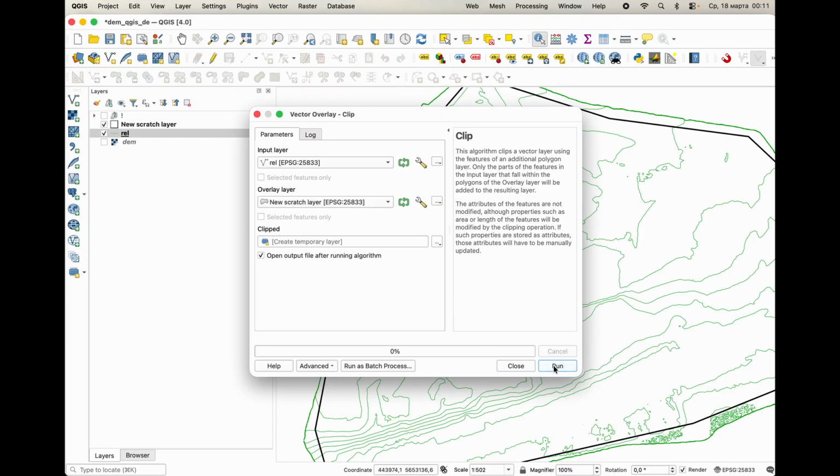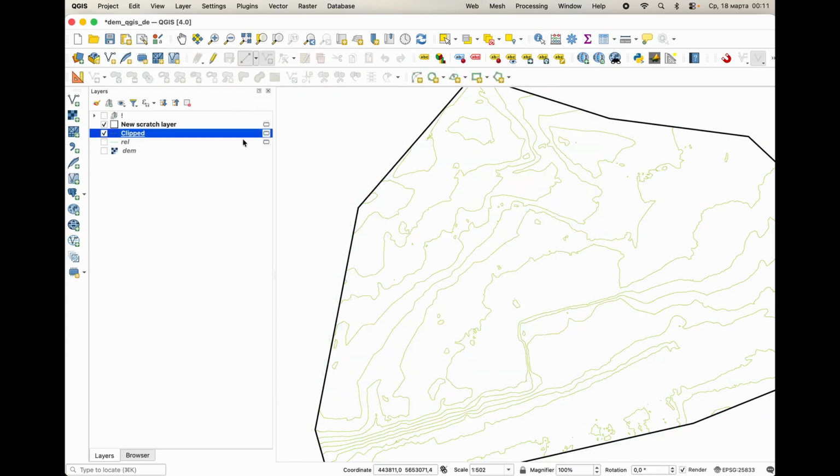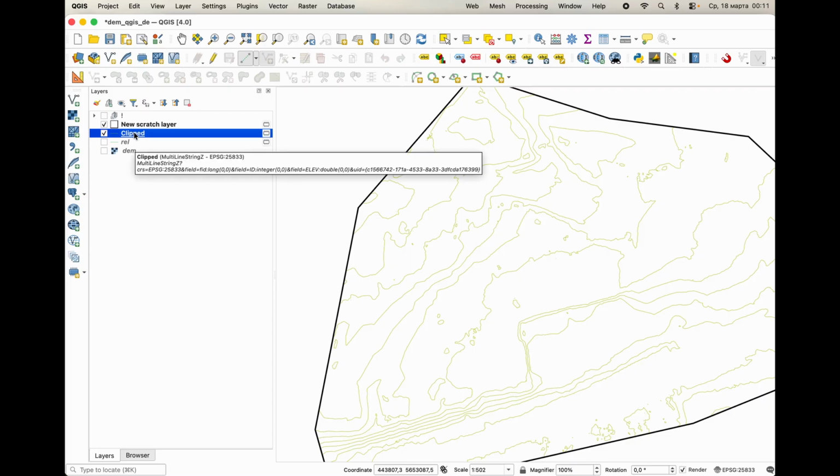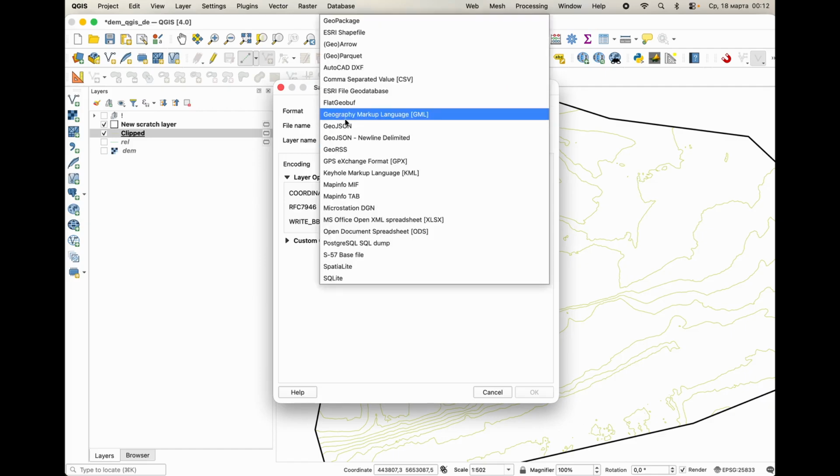The contour lines can be stored in almost any common vector format, depending on what is needed later in the project. For example, we can save them as a shapefile, geopackage layer, or another standard GIS format. At this stage, the geometry is already much more usable, but there's still more refinement to do.